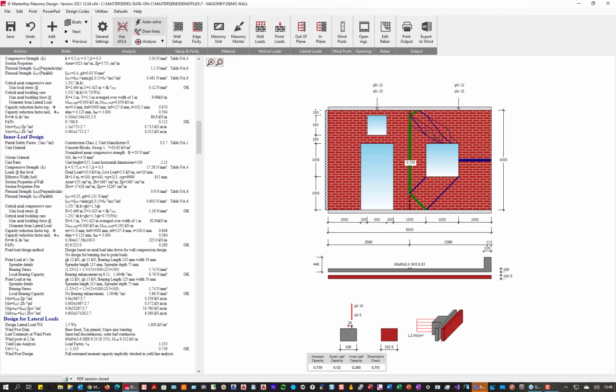And if we're on an upper floor, then it's a more clear cut. Is it on a sill or is it just continuous? On you go. You don't need to use the normalized block strength, so not 10.4 but equivalent. We actually do use the equivalent values for those normalized ones.